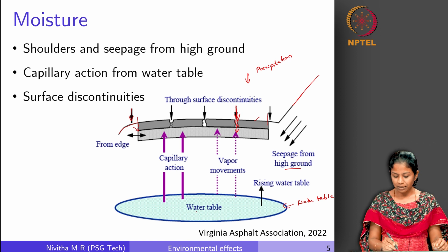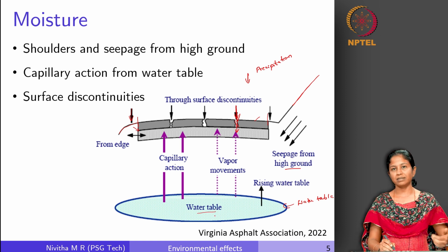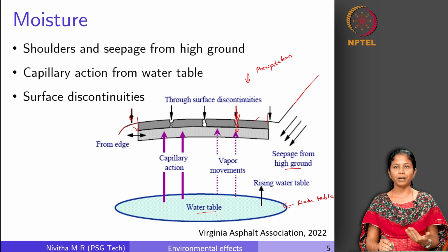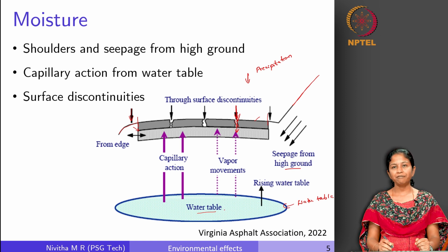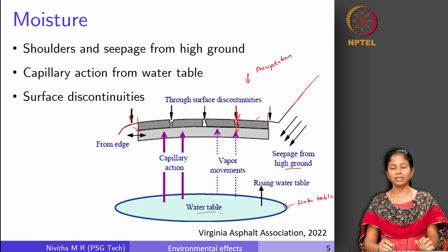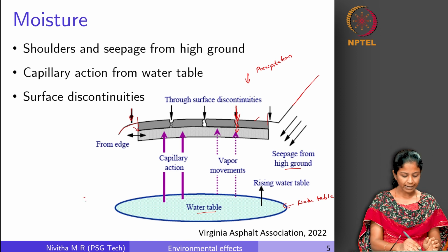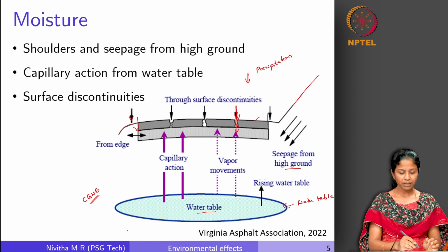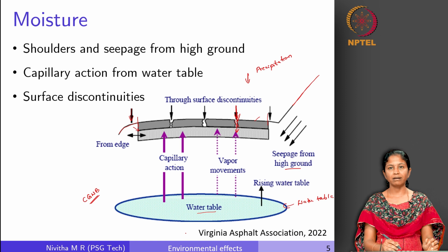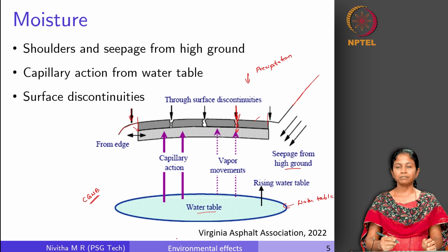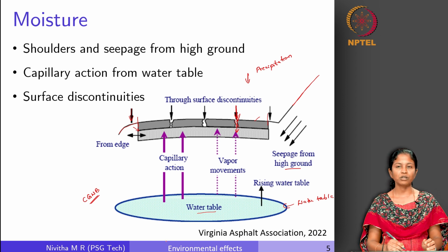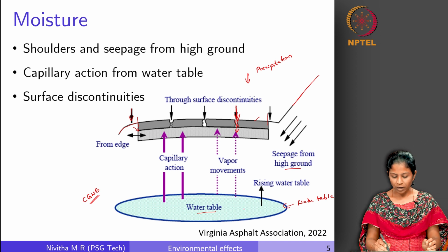The next aspect is water table, right. So, there is water table at different depths depending upon the location. Information about water table is commonly available, otherwise this Central Groundwater Board, I am not exactly sure, but there is something similar to this, a Central Groundwater Board which prepares these maps which indicate groundwater table at different locations. So, from these kind of sources also we will be able to get information on the water table, right. So, we have water table.